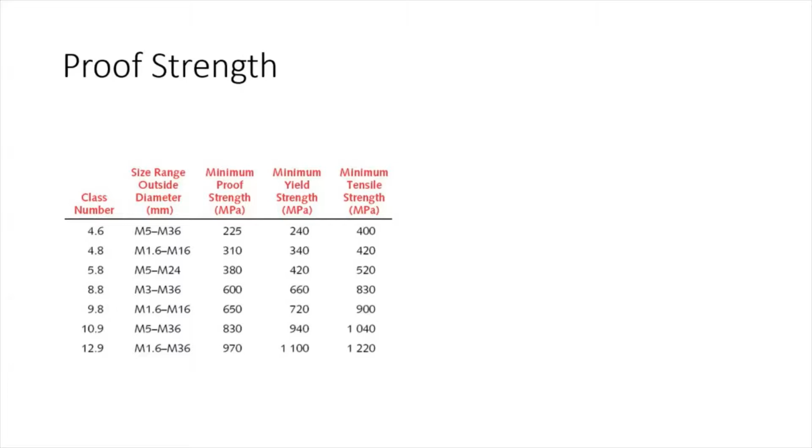In the hint, it is said that the fasteners are preloaded up to 90% of their proof strength in static loading. And let's remember what the definition of the proof strength was. The proof load is the maximum load that a bolt can withstand without acquiring a permanent set. Permanent set means there is plastic deformation.